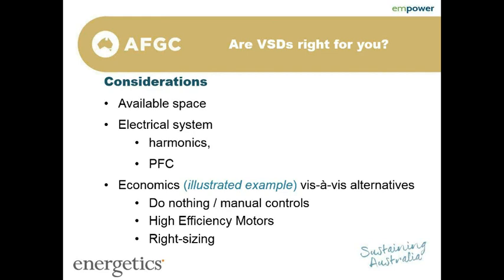And then in line with that is whether right sizing of that motor is an option for you. Often motors will be oversized, planning on expansions when things are installed, or just wanting to make sure you've got enough capacity. Oversizing motors is fairly common, and can result in the motor using unnecessary power for that bit of kit.